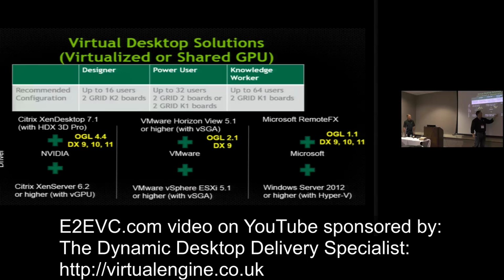While it will run in this particular scenario, what if I'm running Pro-E? Is that an OpenGL app or a DX app? Anybody know? Or CATIA or SolidWorks? They are OpenGL applications. OpenGL in its current form today is at Rev 4.4. So while SolidWorks and CATIA or Pro-E or some of these big design applications may run, because I don't get OpenGL support up to 4 point whatever, the current one today, I'm going to fall back to CPU rendering. So I'm really not taking advantage of the GPU as much as I want to, okay? So these work awesome in specific situations with specific applications. You've got to know the apps, you've got to know what graphics API calls are being used to determine which one's the best fit for you.